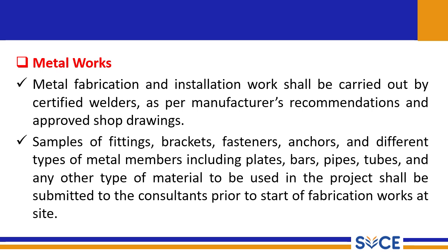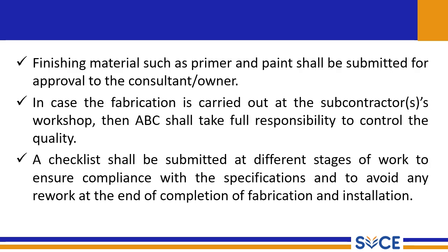So, whenever possible, we need to collect all the material manufacturer's recommendations and approval requirements and approved drawings, and we have to submit them to the consultant for quality testing. Okay, so we need to make sure it is okay to use this material on the site. Only then can we go for using it for fabrication works. Finishing materials such as primers and paint shall be submitted for approval to the consultant or owner.